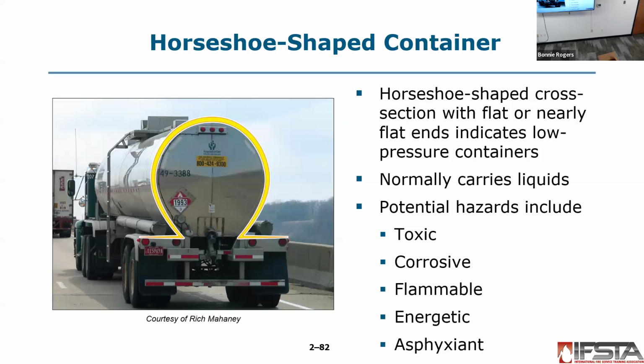That's the guide number. Okay, so does it matter if it's a weed killer or a diesel fuel when we have a spill? No. We're going to look at what it tells us to do. Eliminate all emission sources. Put your cigarette out. All equipment must be grounded. And petrol. Include your radio? Yeah, what else?